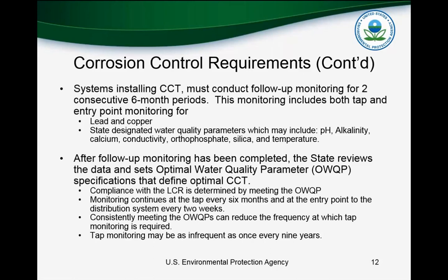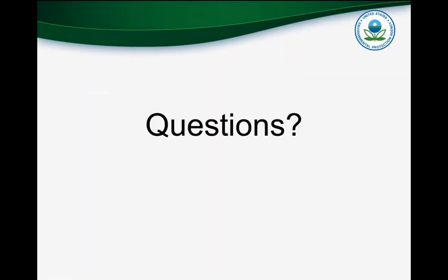Monitoring continues at the tap every 6 months and at the entry point every 2 weeks. And if you consistently meet your parameters, you can reduce the frequency at which the tap monitoring is required. And once again, as we discussed prior, the monitoring can be as infrequent as once every 9 years through continued compliance. And that's all I have, although it sounds like we hold questions till the end.